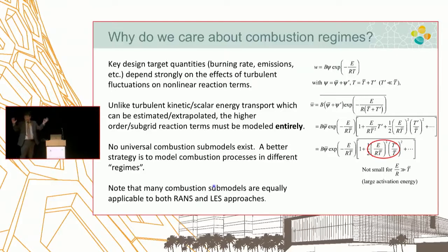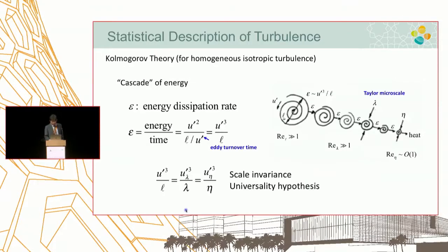So that's the whole picture here, and that's the main discussion we're going to have. I will first talk about how we characterize the combustion regimes, and we will talk about what we do. Without these, you do DNS. Great, you can resolve everything, but you can't do so much. So we'll end up doing LES and RANS, and then we'll have to worry about subgrid and Reynolds modeling.